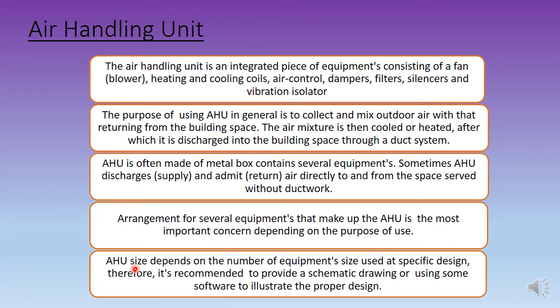The size of the AHU depends on the equipment sizes, and we have to see what application it is for. Therefore it is recommended to provide a schematic drawing or use any software to illustrate the proper design, so that we know the actual size of the AHU after we choose all the components.